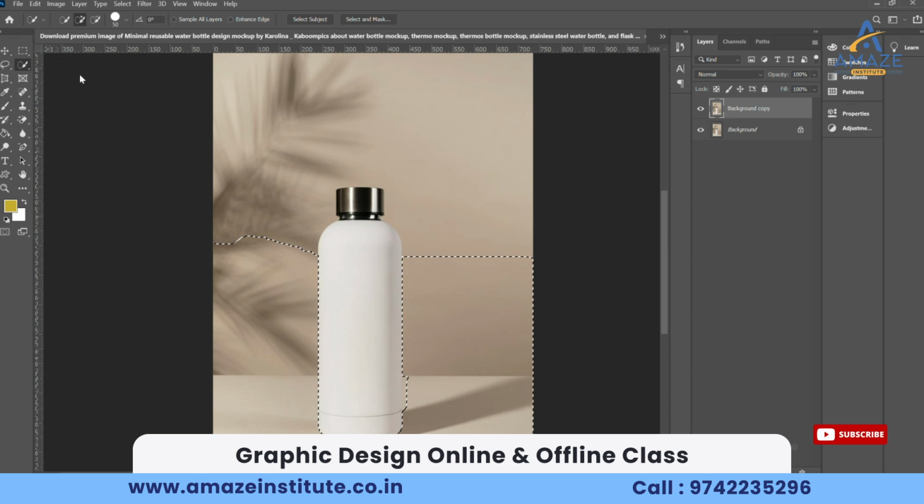And if you want to minus the selection, now I'm going to the minus mode. The same thing is there. The brush size, if I want to increase or decrease, I can do it. And from outside, if I drag like this, now it's being deselected. Now the selection is being removed. You can see the selection is being removed. That is the thing, Akansha, you can remember. If you press plus, from inside the selection if you push, it's added. Minus means it's removed like that.